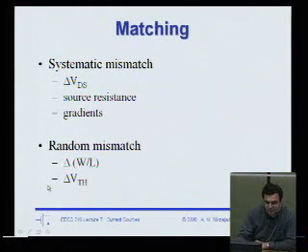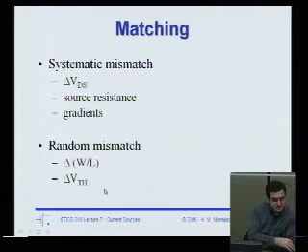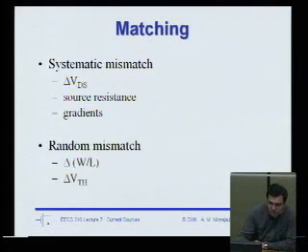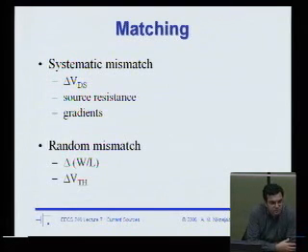And if you actually now look at how that impacts, let's say in particular a current source, the threshold voltage is going to vary, doping variations and so on and so forth. And also there's going to be lithographic variations. We're designing very small transistors, so when you put down 1 micron, it's going to be 1 micron plus delta. More importantly, the channel length is very small, and it's 0.1 micron or 0.18 micron, and it's going to vary, and that's going to introduce variations.